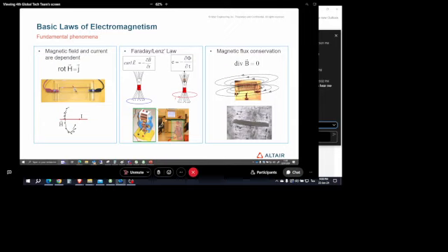The magnetic field on the stator is created by the winding. The winding is actually an electric cable that we supply. When we supply an electric cable, we create a magnetic field. This magnetic field surrounds the cable and is expressed by a mathematical equation: the curl of H equals J, where J is the current density. This is what happens in the winding.